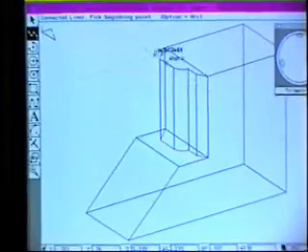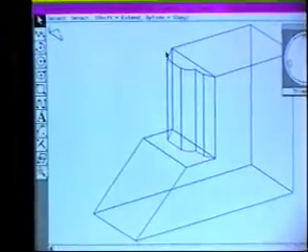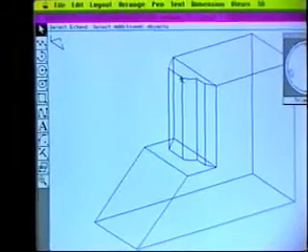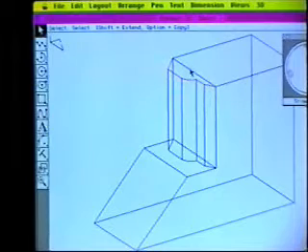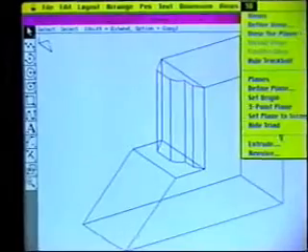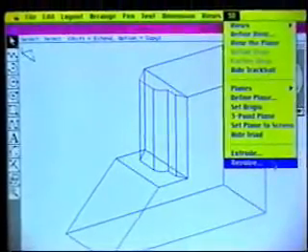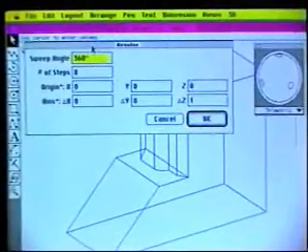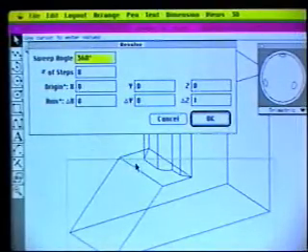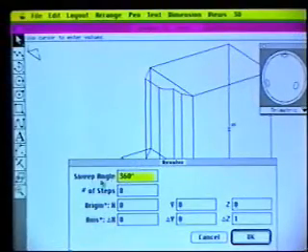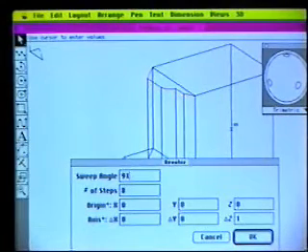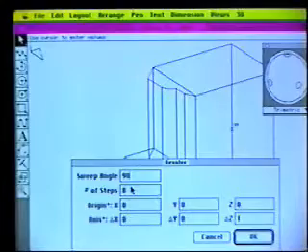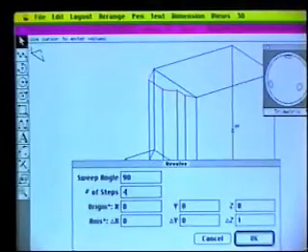Now I'm going to pick my arrow tool and select these 5 objects at the top of my contour, and I'm going to rotate those around this line as an axis. So I'm going to sweep it, or in this case we use the word revolve. Again, this box I can move out of the way. Here it's easy to see that I want a 90-degree rotation, so I can type 90, and rather than 8 I only want 4 steps.